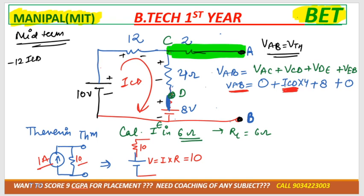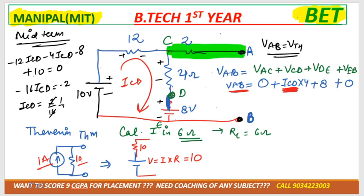That would be minus 12 ICD minus 4 ICD minus 8 plus 10 is equal to 0. So minus 16 ICD minus 8 plus 10 plus 2 equal to minus 2. So ICD is how much? 2 by 16, 1 by 8. 1 by 8 into 4 plus 8. So that would be 1 by 2, that is 0.5, 8.5. So the final VTH value you got is 8.5.